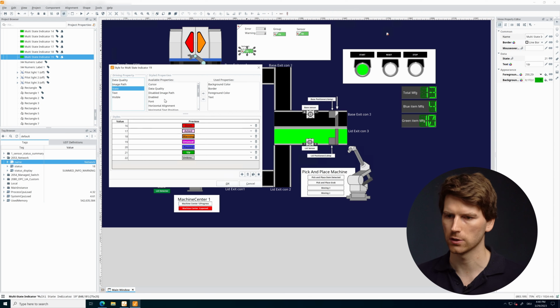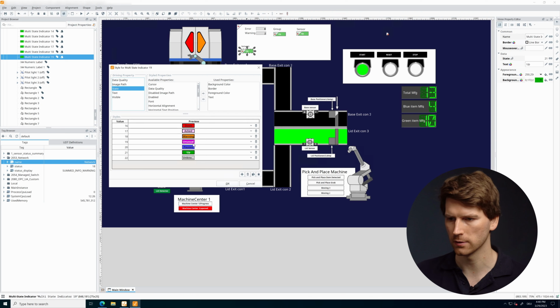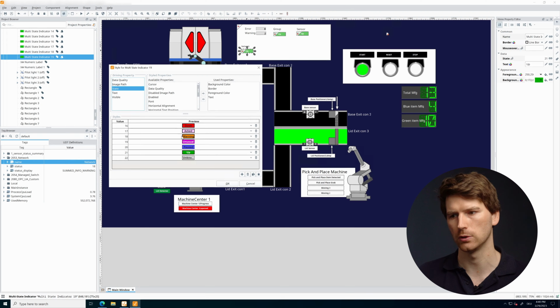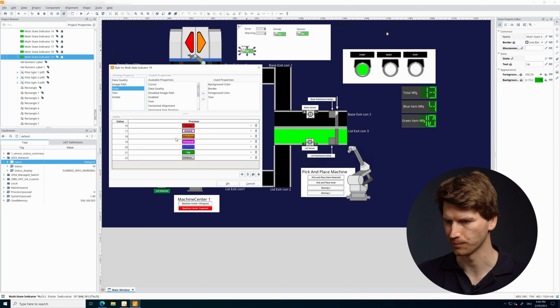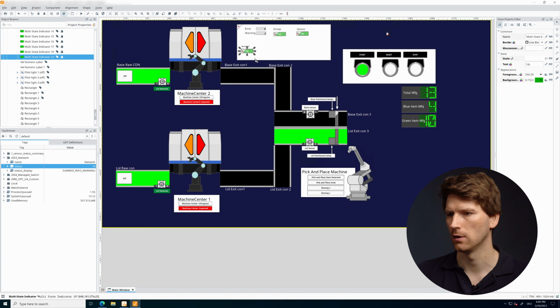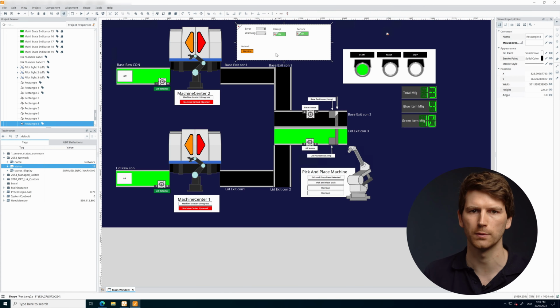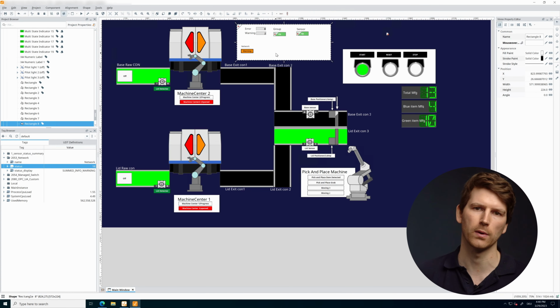For example, here in Ignition, we can map the value we get from PRTG to a proper state of this button. So I already associated 16 with down, 17 with acknowledged, and all these states. This is properly documented in the documentation we provide with the OPC UA server, so you can do this mapping depending on your requirements on your own in your supervisory and control system. So I just go OK here, and now I simply drag the status of our network object over here, and we can clearly see that now our network group is in warning state, so that's good enough. He can now see that there is something going on and is aware of the situation.